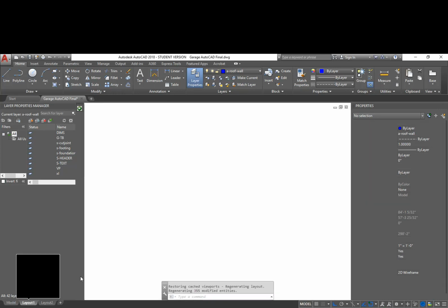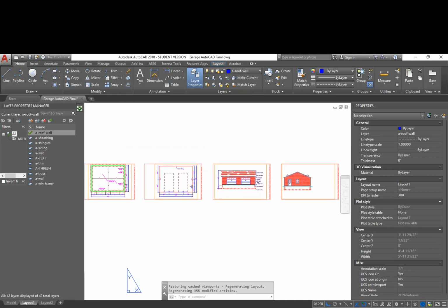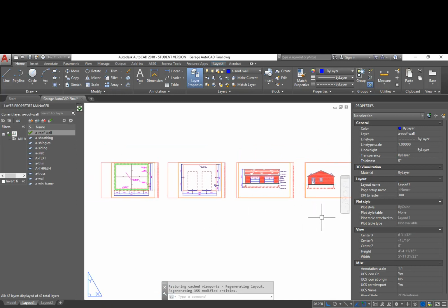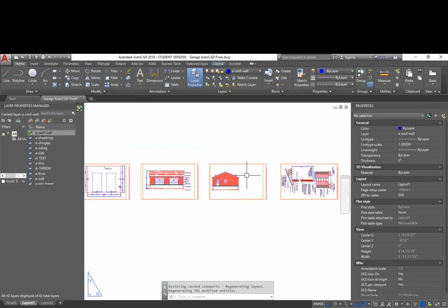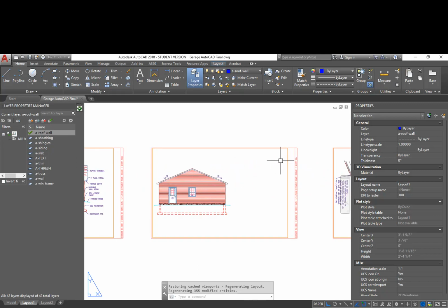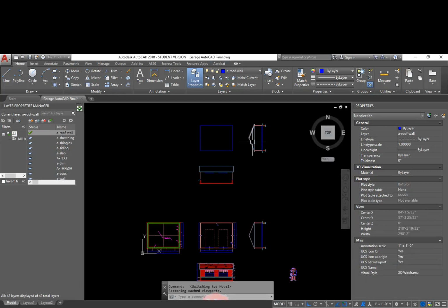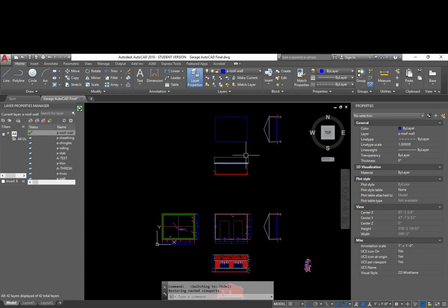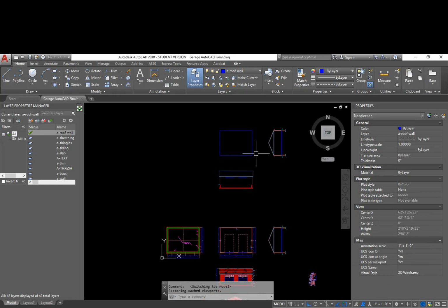What I'm going to do instead, and whenever I look at how my sheets are laid out, basically what I want to do is I want to have my roof plan live right here, and I want to have my building section live right here. There's really not many annotations or detail that's going to show up on either of them, so I'm going to make those both a smaller scale. So to figure out what scale I actually want to use, I'm going to take this outline.